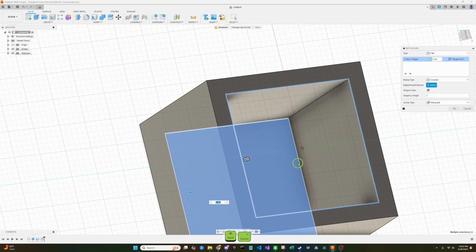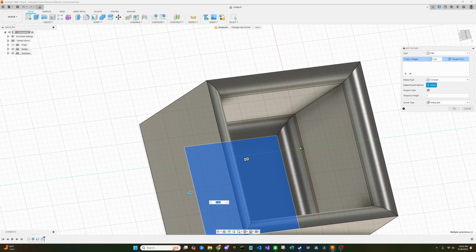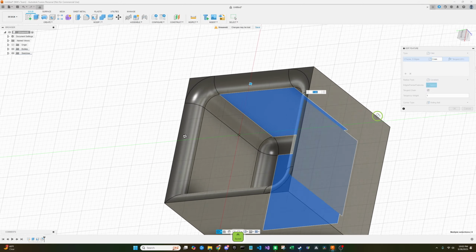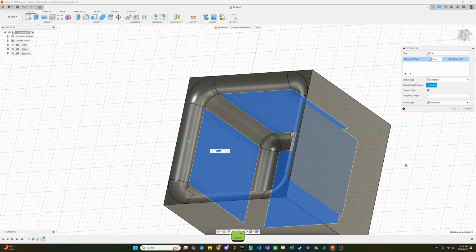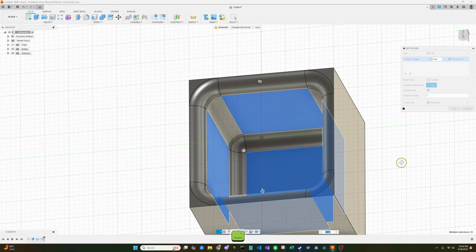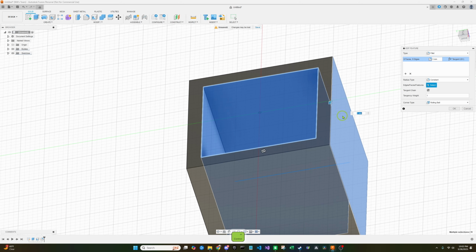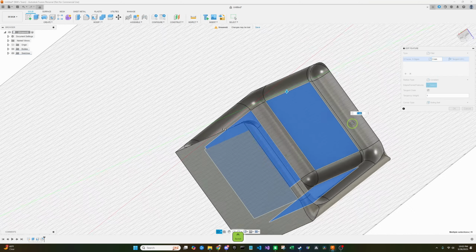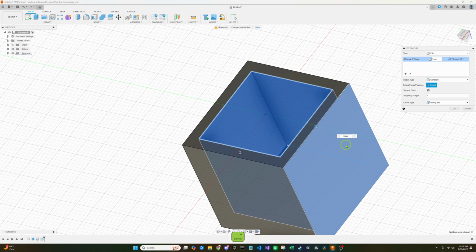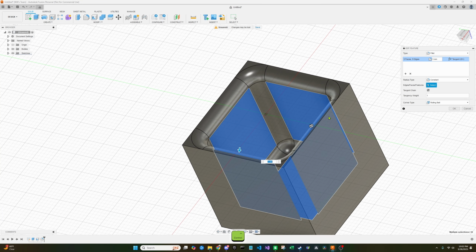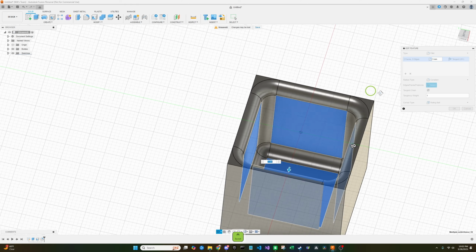Alternatively, if you want all of the surfaces to be rounded, you can select the entire face that you want. So if we select all these faces, it'll round every edge connected to that face. So sometimes this can be a quicker way to do it if that's what you want. So we're just going to go ahead and, ooh, no, not that. The tool can sometimes act funny, especially when you're using larger radiuses like this. So we're not going to select that face.